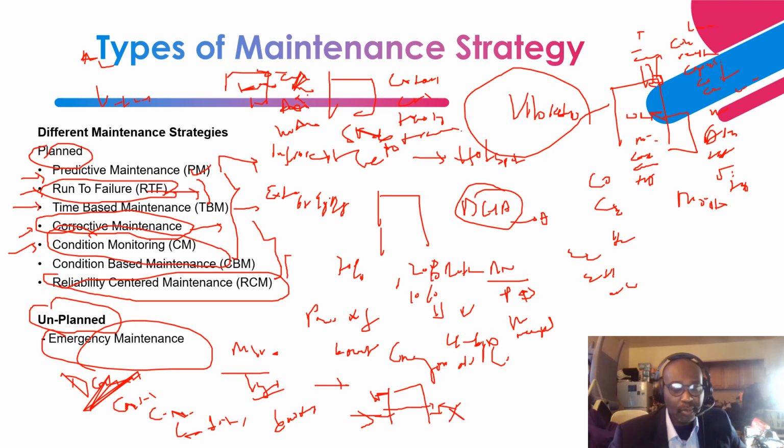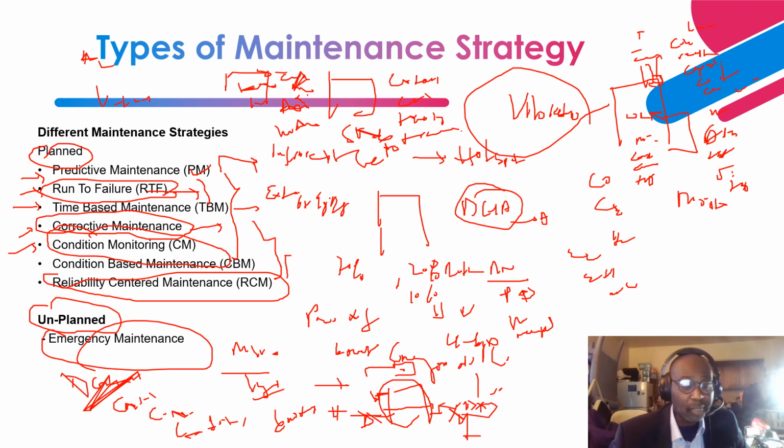The fault is going to go through the transformer from the high voltage side and from the utility source onto the faulted point. So when you have that, what will the circuit breaker do? The protective relay, either the differential relay or the backup 50/51 relay, or maybe the sudden pressure relay, will trip the power transformer and take it out of service by tripping both the high voltage side and the low voltage side. When you do that, you have to perform emergency maintenance inspection and testing on the power transformer.